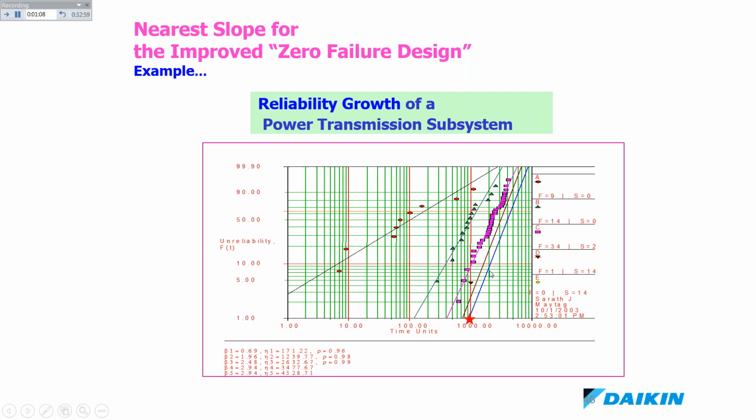So in the last one, you have zero failures, but you can borrow the beta parameter from the other one, analyze, and even draw the line. That's the idea: borrowing from the nearest zero-failure design, borrow the slope from the nearest slope.